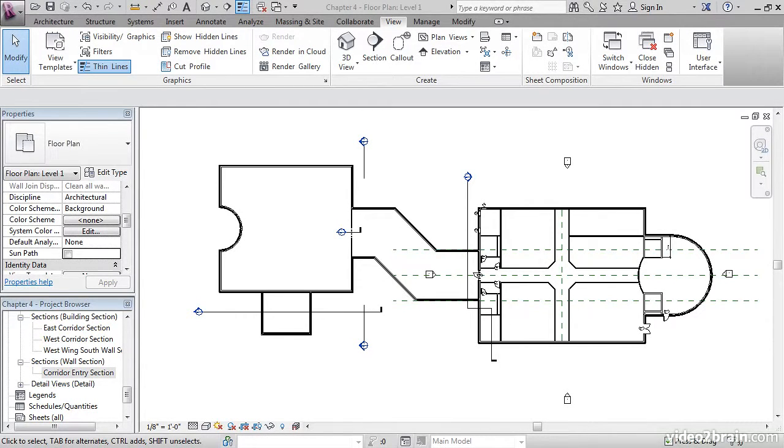In this lesson, we're going to create some callouts. Yes, callouts are still just another type of view. In fact, they are very similar to a section. What a callout does is takes an area of a view and creates a new view by enlarging the scale of the area. Just like a detail, callouts are dynamically linked to the original plan or section in which it was created. The objective of this exercise is to create a callout for a section in the lavatories.